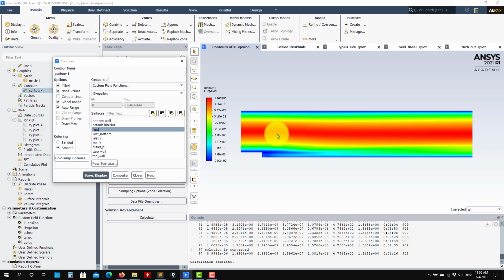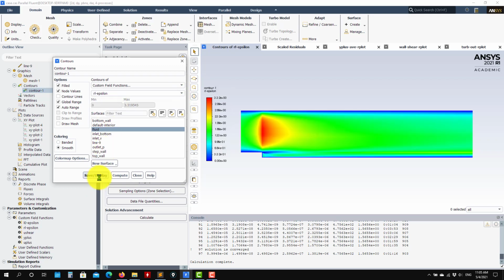Now this is computed from the turbulence model, and then we have RL, which is an indication that will let you know if you need more cells to better capture those integral length scales. We talked about that, the minimum should be something about 5, but remember that is for scale resolving simulations.